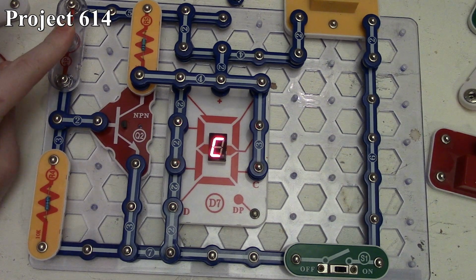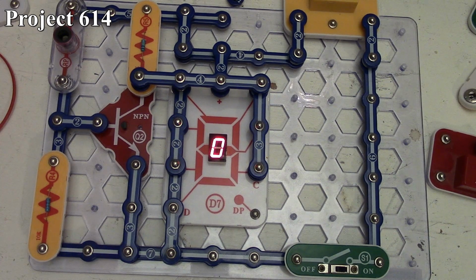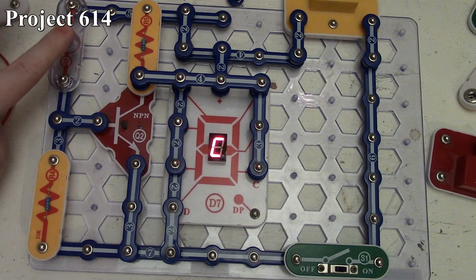Now if we close up our photoresistor, we're taking current away from our NPN transistor, thus it's not turned on, so the segments on this side do not light up, and it leaves us with the letter C to mean closed. And we let the light back in, our transistor turns back on, lighting up these segments, and now we get O back on there.